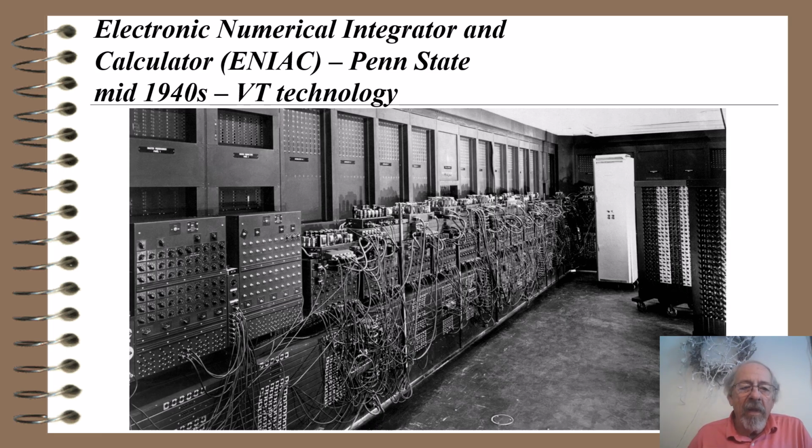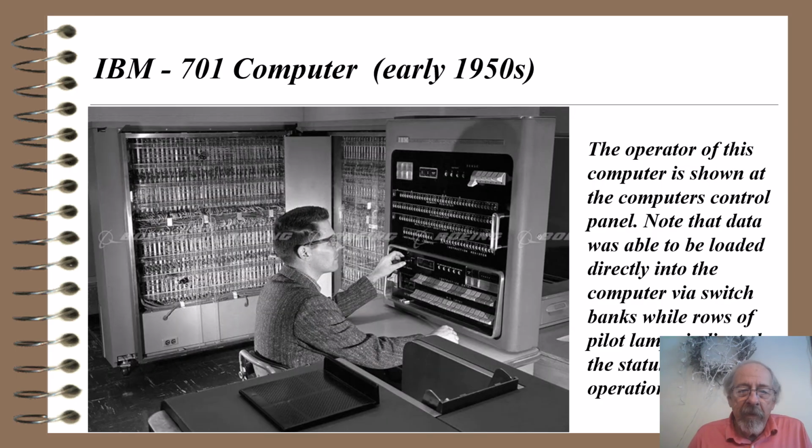Because of reliability, people knew about what they called infant mortality. You first turn an electronic device on, it's prone to failure, then you have old age. In between infant and old age, there tends to be a constant mean time between failures. But again, if they didn't burn in the vacuum tubes, the calculations were this thing wouldn't keep running for long at all.